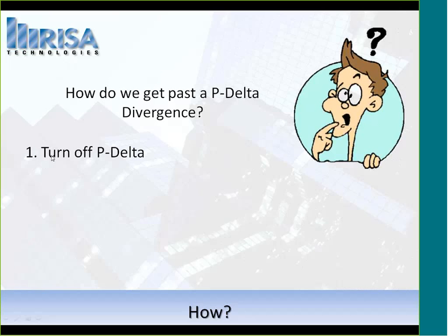So what we do is we just turn off P-Delta for any load combinations, maybe all of the load combinations, and go from there. We'll also obviously run the model. Once you have P-Delta off, you should be able to get past that. So now you can see what's happening in the model. And then the next step will be to review deflection. So the deflected shape will give you so much of a picture of what's happening in your model. A picture is worth a million words. It's great to understand exactly what's happening in the model, and it will give you a lot of clues.